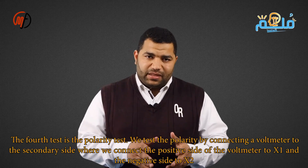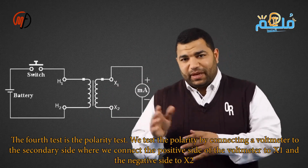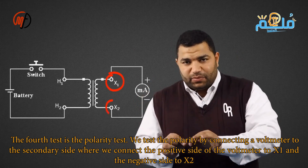The fourth test is the polarity test. Connect a voltmeter to the secondary, positive to X1, negative to X2. Connect a DC battery to the primary, positive to H1, negative to H2 via a switch. Press the switch. If the needle or DC reading is positive, polarity is correct.